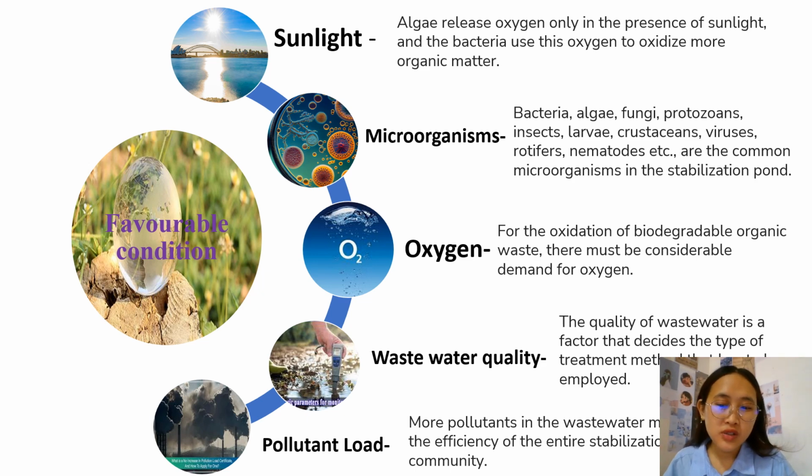And oxygen: for the oxidation of biodegradable organic waste, there must be considerable demand for oxygen, right? And wastewater quality: the quality of wastewater is a factor that decides the type of treatment method that will be employed. And pollution load: more pollutants in the wastewater may affect the efficiency of the entire stabilization pond community.